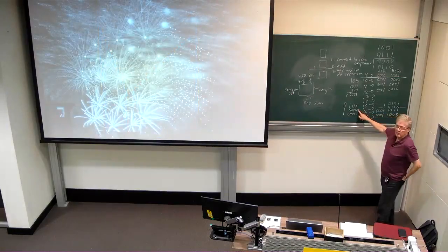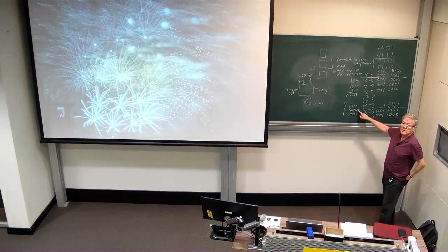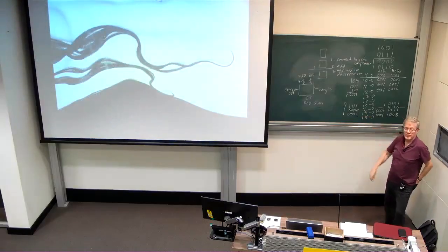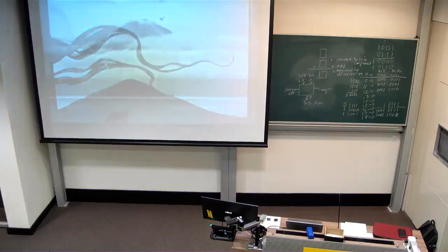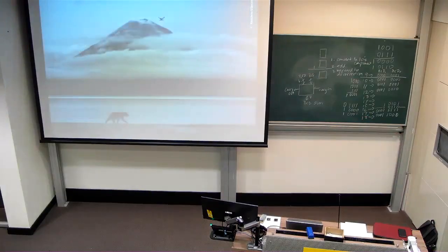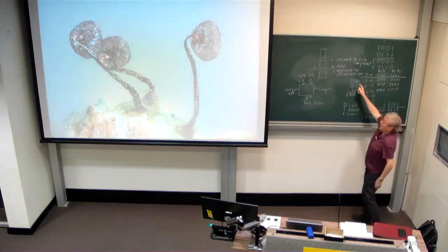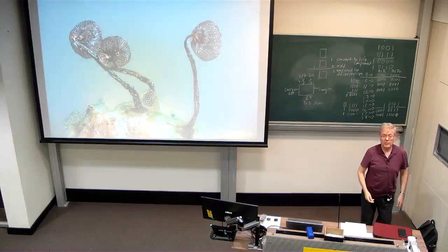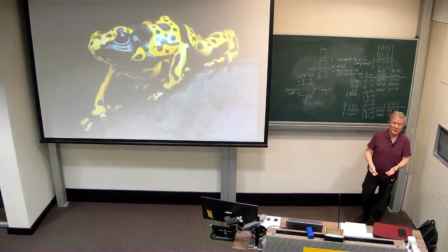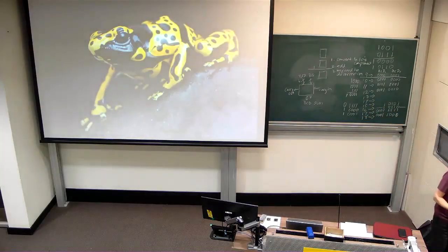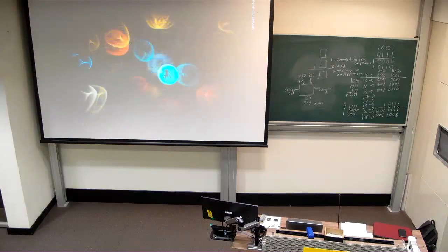How does that solve this case? Oh, so you have to put another OR. So I think you have to check you've got a carry or you've got 10 or more in your sum, right? And in that case, we just want to add another 6. And the result should be fine. Okay?